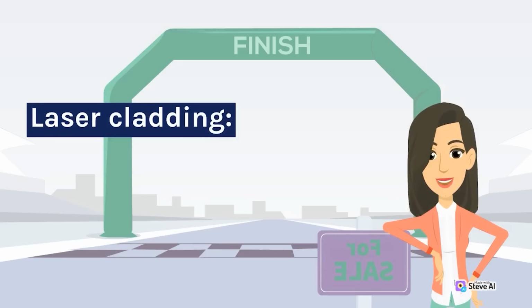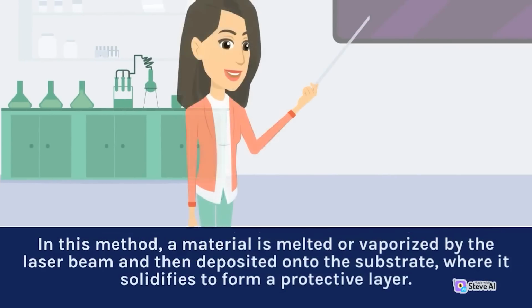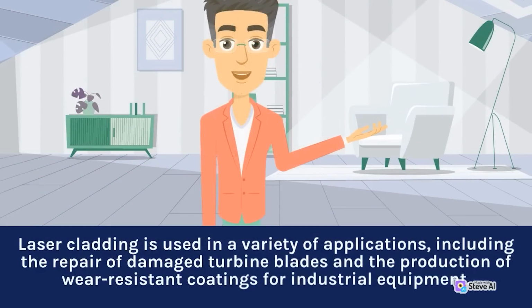Laser cladding. Laser cladding is a process used to create a protective layer on a substrate using a high-energy laser beam. In this method, a material is melted or vaporized by the laser beam and then deposited onto the substrate, where it solidifies to form a protective layer. Laser cladding is used in a variety of applications, including the repair of damaged turbine blades and the production of wear-resistant coatings for industrial equipment.